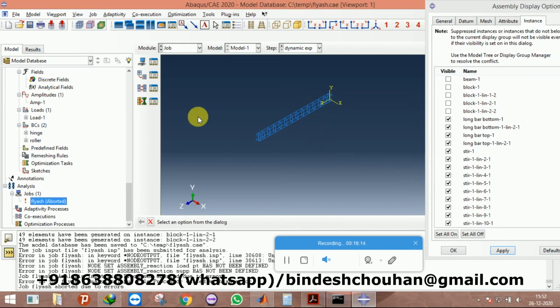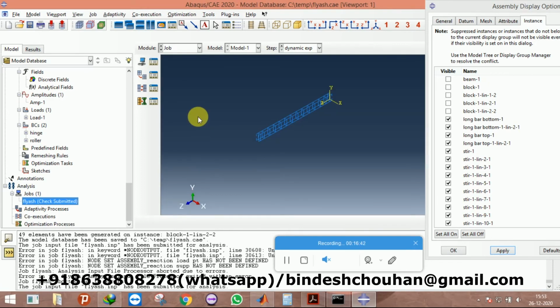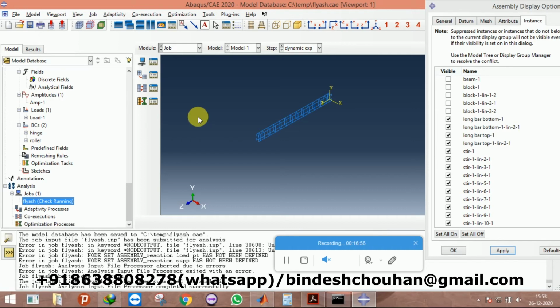I'm getting this because previously I tried to model it using rigid block, but there was some issue, which is why I had to change it. When I was trying to model it using the rigid block, you have to assign some boundary condition to the translation degree of freedom of each rigid body, but because I was applying the load, not the displacement, since the analysis was load control, I had to leave this particular displacement of the rigid body free, which is why Abaqus was not accepting it. Because of that I have this issue.